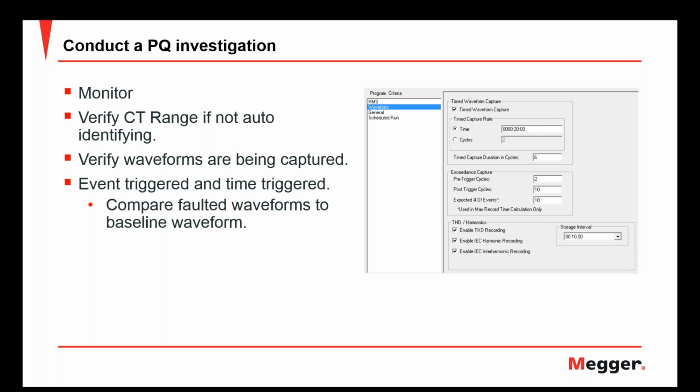So they have a lot of value to them in that they give you a baseline reference to start with. And also it's ideal for doing a harmonic analysis on them, because that detailed harmonic analysis on a time-triggered waveform will let you know what your load is. And again, I don't have enough time to go into that in this presentation, but in future ones, we will cover more about analyzing harmonics and determining your load based upon the harmonic content of the timed waveform.